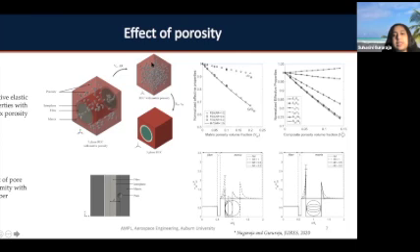There are obviously things like the proximity of certain pores, and the geometry of certain pores in relation to, say, the fiber, that have to be studied separately. But by and large, if you capture the distribution of the pores and identify the important parameters, you could have a matrix phase inclusive of the process defects that you could use to predict what the performance is going to be.